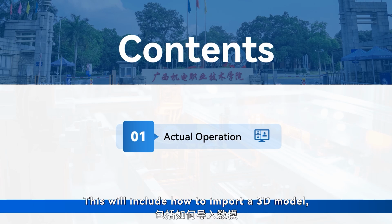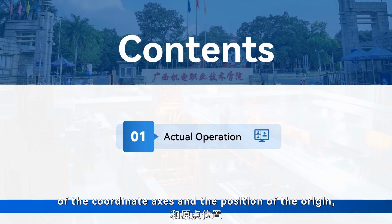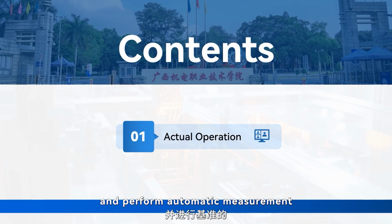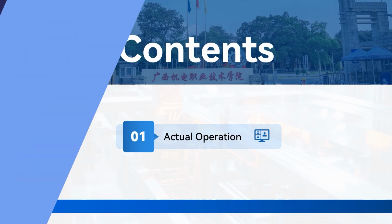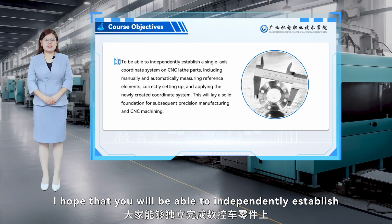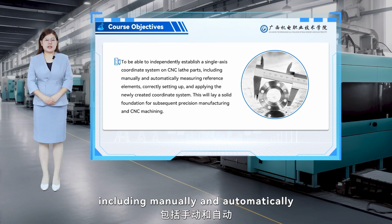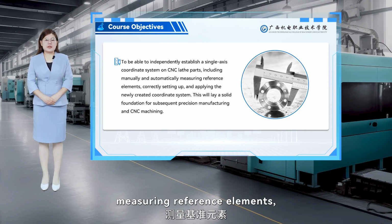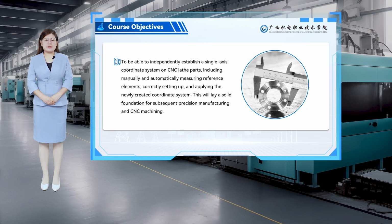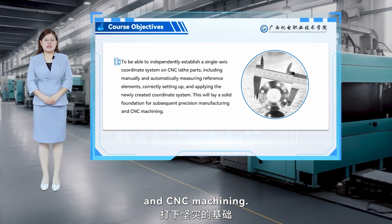This will include how to import a 3D model, how to measure and determine the direction of the coordinate axis and the position of the origin, as well as how to set up the safety space and perform automatic measurement of the reference points. By the end of today's lesson, I hope that you will be able to independently establish a single-axis coordinate system on CNC lathe parts, including manually and automatically measuring reference elements, correctly setting up, and applying the newly created coordinate system. This will lay a solid foundation for subsequent precision manufacturing and CNC machining.